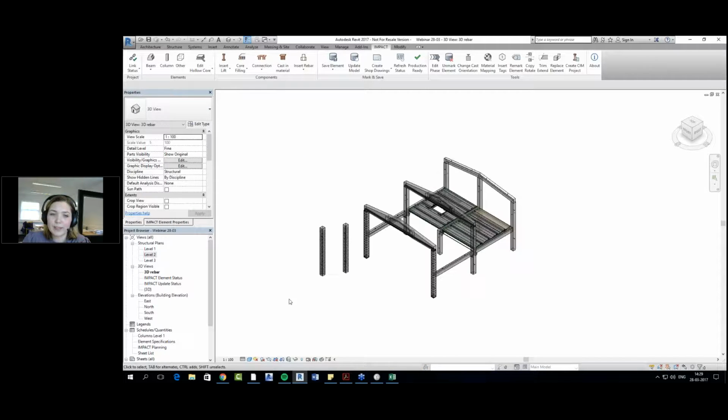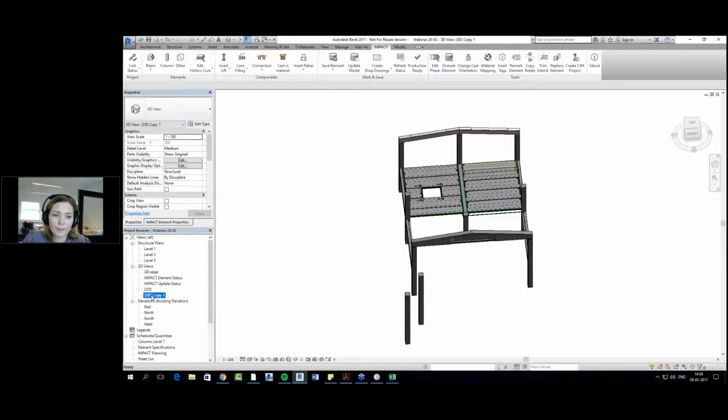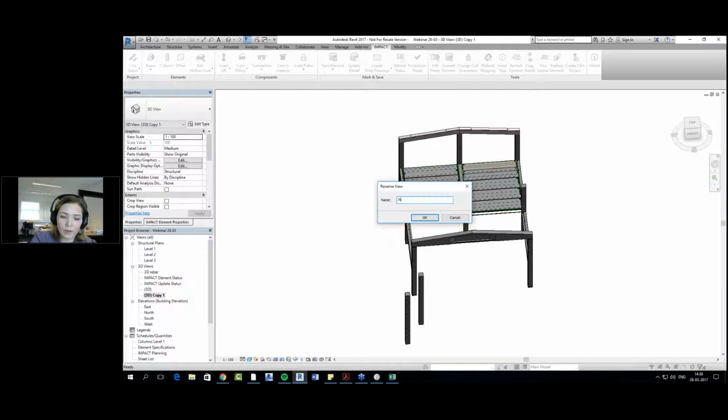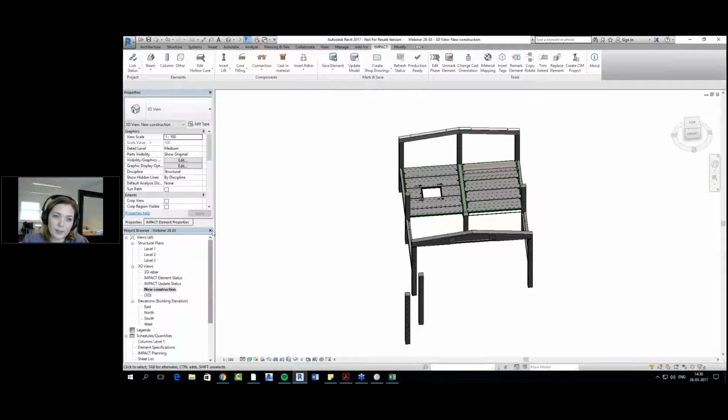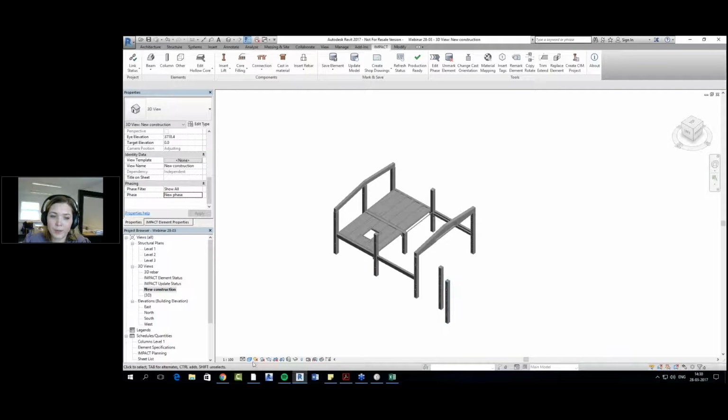So we have those phases. Let's try to create a new 3D preview, which we will call New Construction. So we say that in here, we want to see the new phase. And if I scroll down, there is already predefined phase, existing phase, but let's say that this is supposed to be a new phase. All elements are grayed out now.